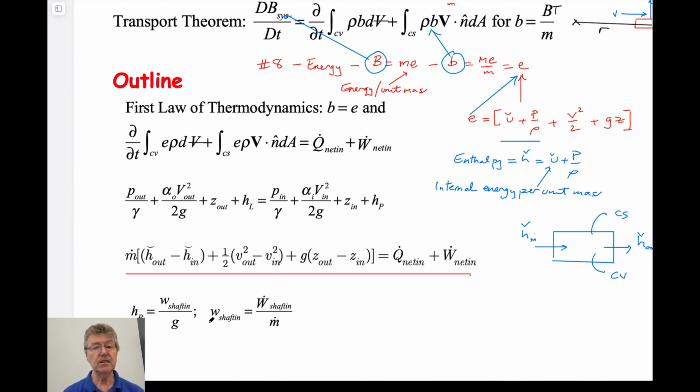And so I'm not sure there's a whole lot more to it than just saying that we've added a term which now allows us to work with hot fluids, geothermal fluids, for instance, and to be able to say exactly what's going to happen in those systems. And this is the expression that we'll end up using. This is mass rate. This is what we've called uppercase M dot. Not sure what this is doing down here. So it's mass rate, and these are internal energy per mass. And so actually it looks a little strange, I suppose, right?